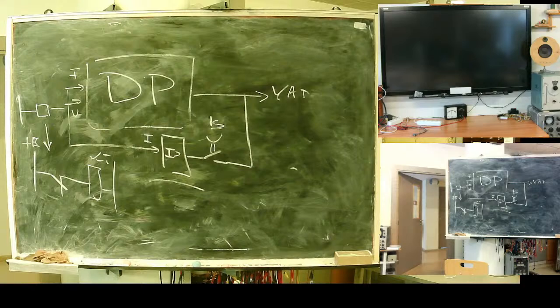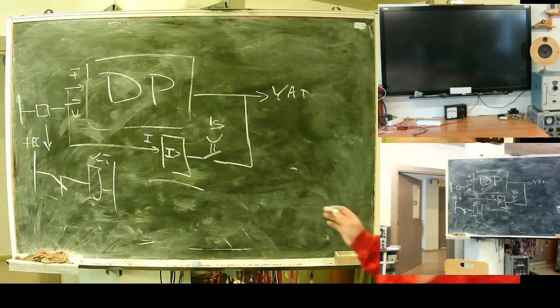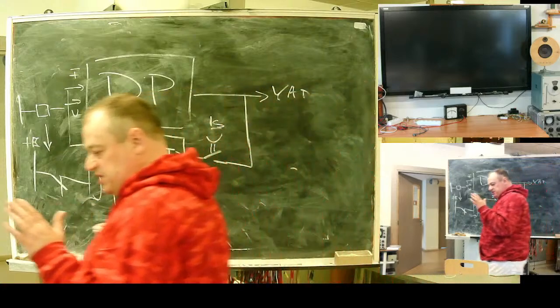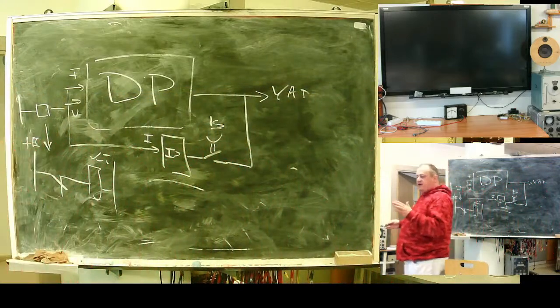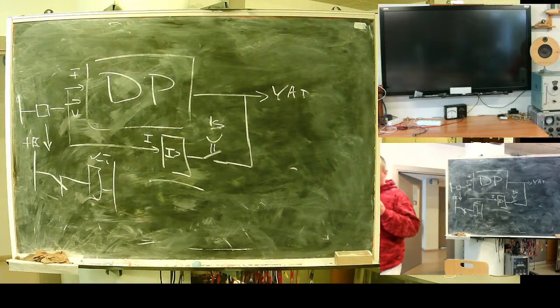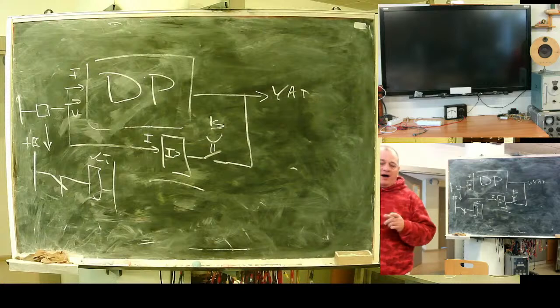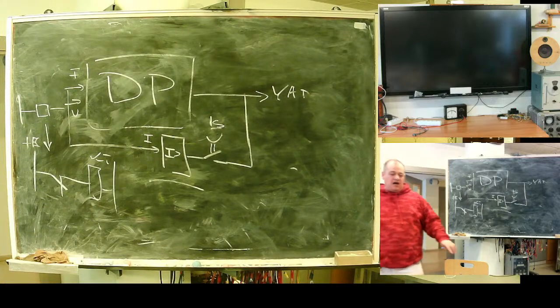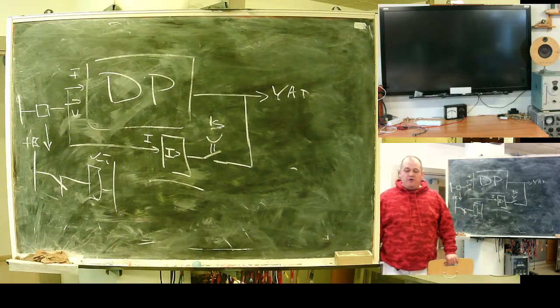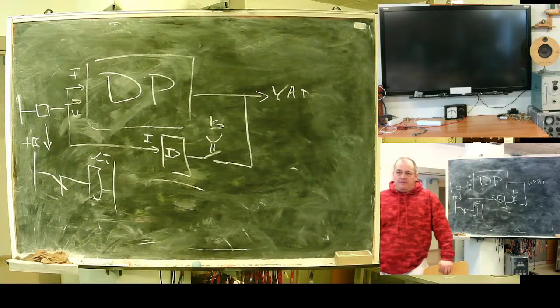It should overlap blind zone of distance protection. Should be activated for short time, only for 1, maybe even less than a second. It should be active till the time distance protection fills its memory.